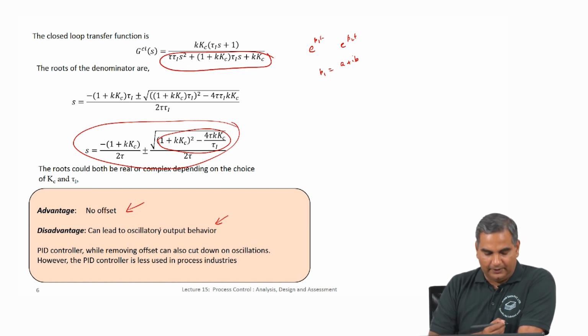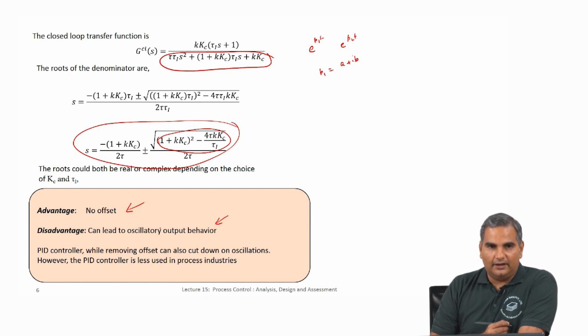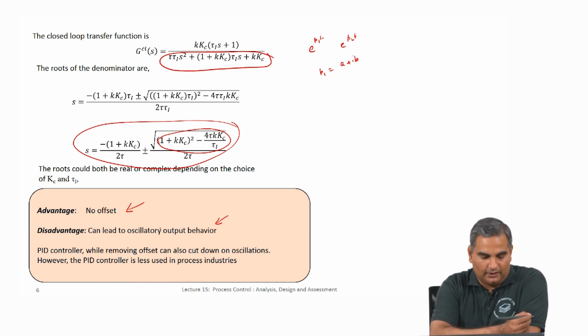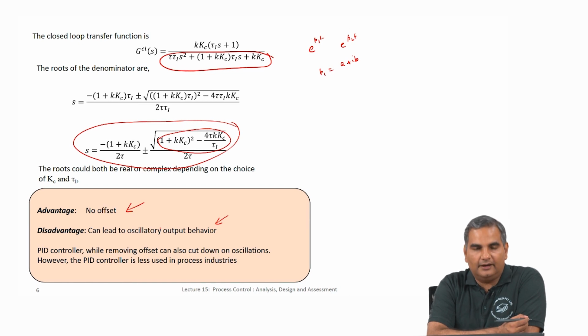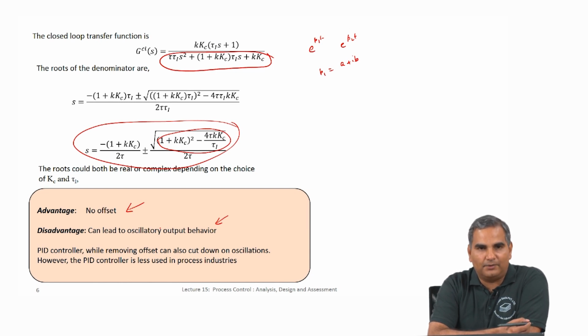Now, we talked about P and PI. The third type of controller is the PID controller. Now, most often you will see in industrial processes either P or PID controller being used. For systems where you are looking at getting a response which is very fast, ease of implementation of a controller, and you really do not care so much about offset, you would implement a P controller.